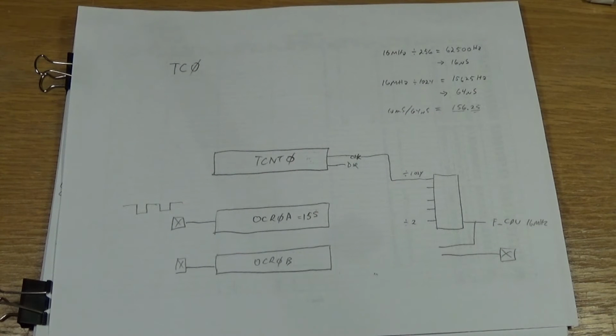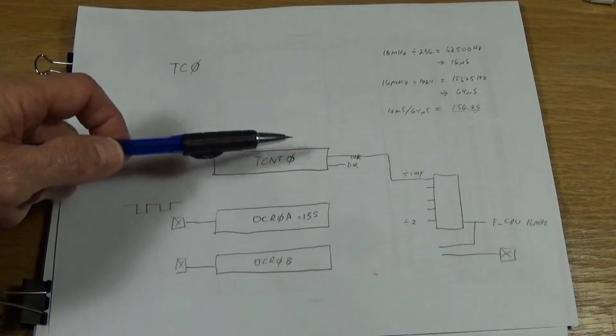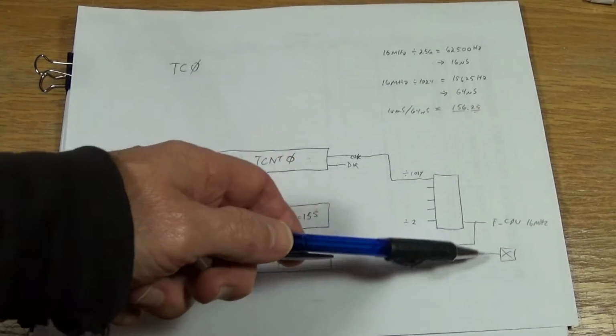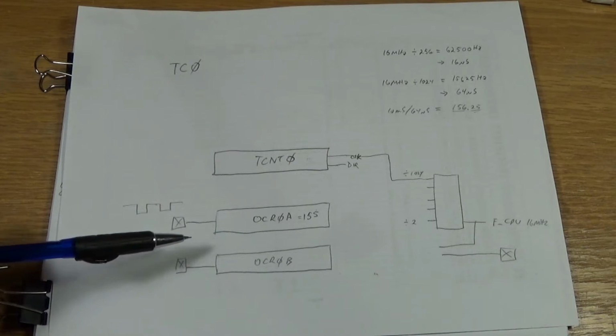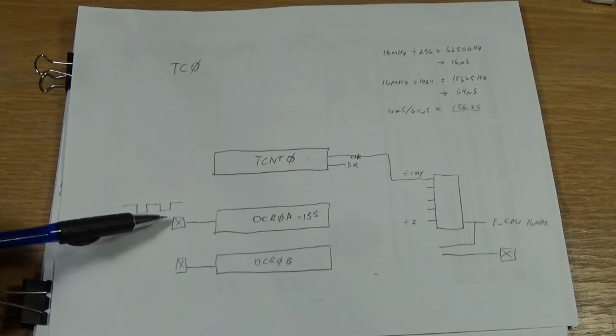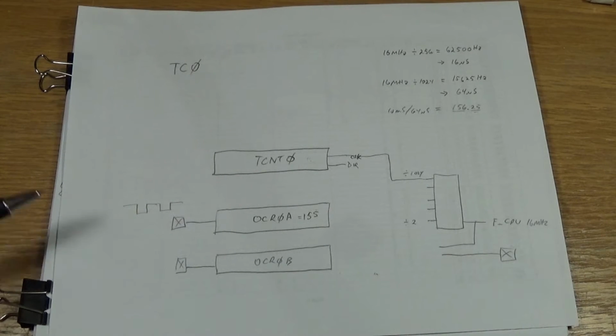In my previous video, I introduced you to one of the timers in the microcontroller, timer counter 0, and I just gave you a brief overview and showed you how to set it up to give a regular interrupt. In this case it was every 10 milliseconds, and I talked about a couple of the registers that are involved with the timer counter. The main counting register that's driven by some oscillator, some frequency, and then these two output compare registers, which when set up appropriately will also toggle an I/O pin. Each of them will toggle an I/O pin.